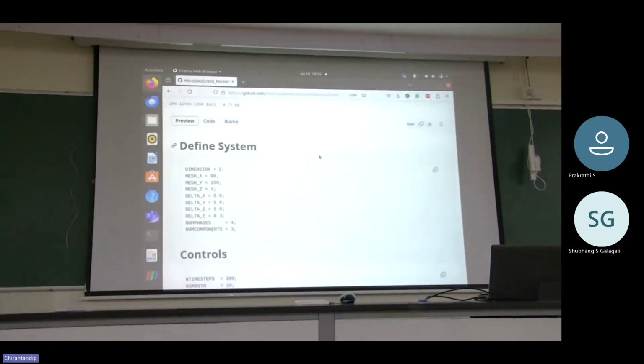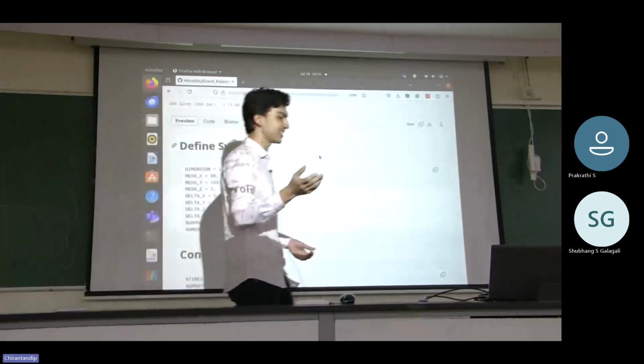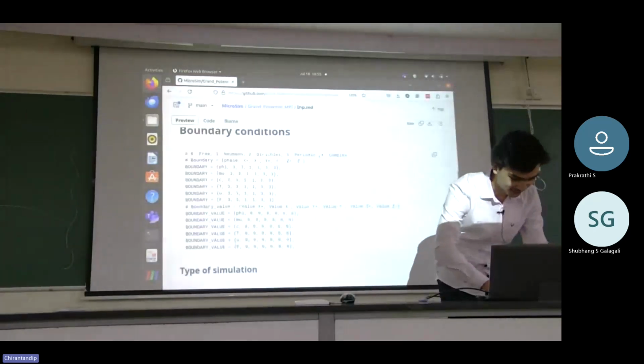So first, what we do is we can only impose boundary conditions in these cells. There are 3 boundary cells in which you can impose these boundary conditions. So if I want to change my far field composition here, I'll have to interpolate it and change it here, which is now in the input file called EIDD, exponentially interpolated Dirichlet, but we can find a better name for it.